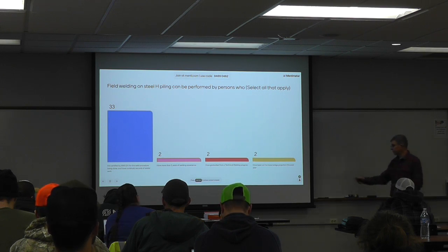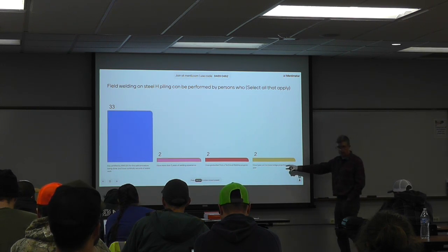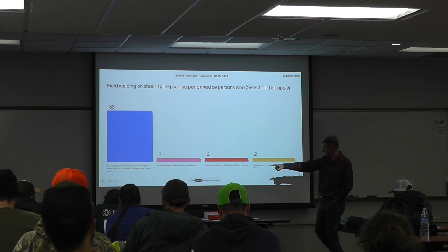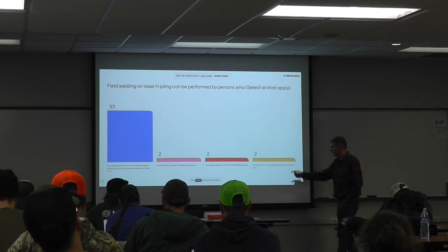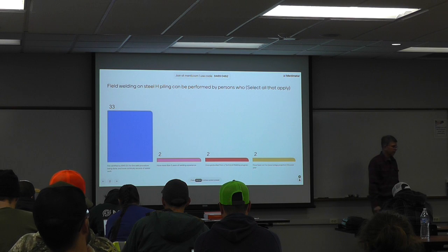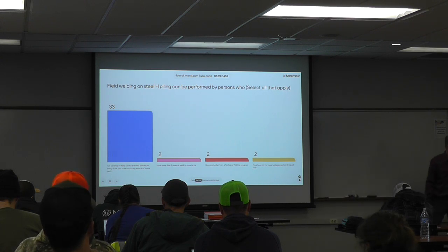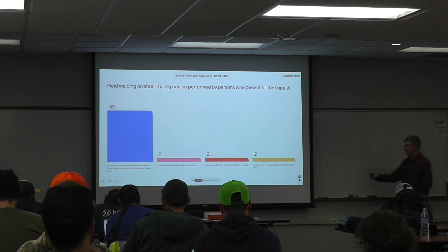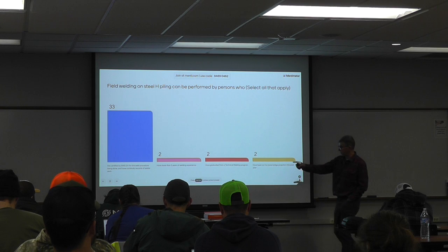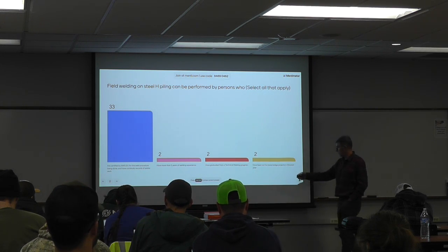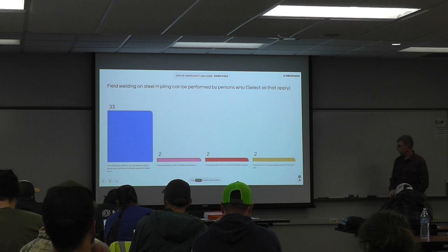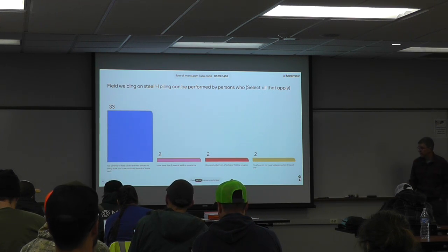The rest of these are good: that they have 3 years of experience, they've graduated from a tech welding program, more than 5 years of welding. But that still doesn't allow you. If you're not certified for the type of weld you're doing, which is in the first column, that would not be adequate. So, AWS D1.1.